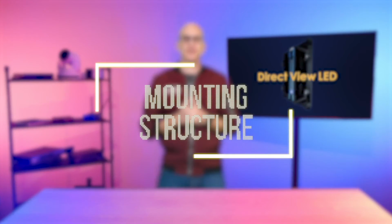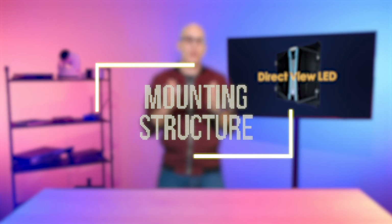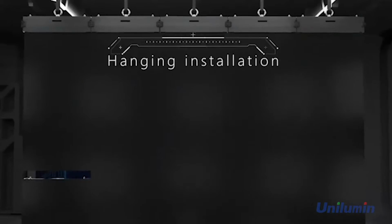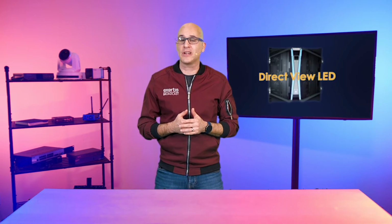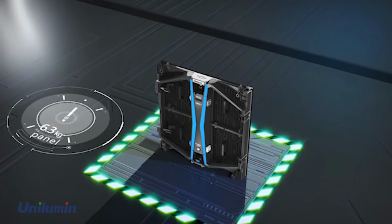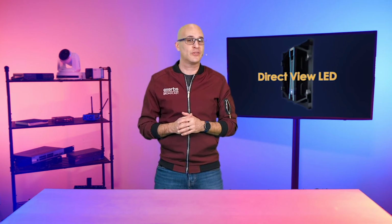Let's think about the mounting structure. A mounting structure is one of the most important aspects of your dvLED wall. Walls can be flown or walls can be mounted permanently. For hanging walls, a structure strong and sturdy enough to hold roughly 64 panels at nearly 700 pounds is a requirement. The same holds true for installed walls.